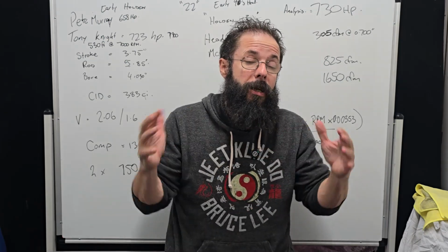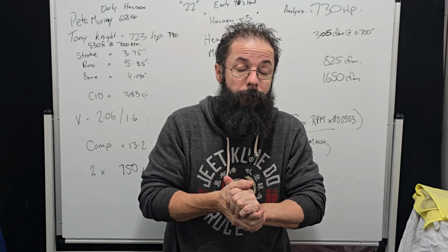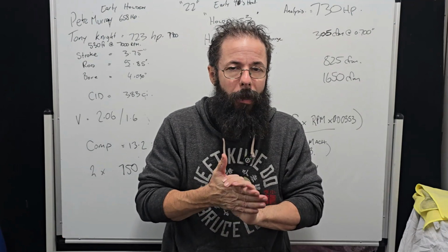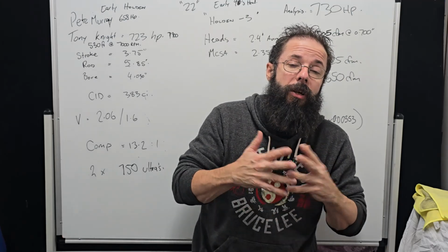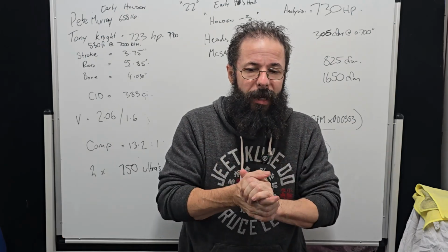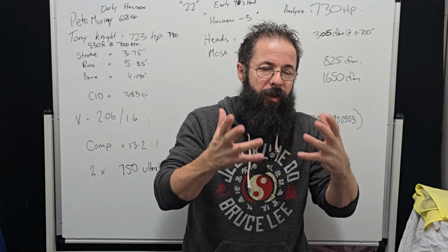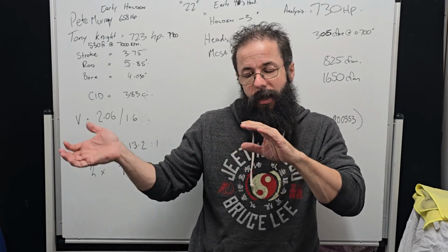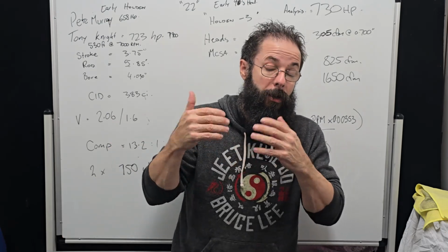So meaning we can go much bigger in the carburetor without sacrificing a lot of low end response that you'd see normally with a single plane, because they're turning the air so hard and the signal gets washed out. And also with a tunnel ram, they generally don't need shear plates or anti-reversion plates. And this is where you'll see a lot of people get confused with over-carbureting dual planes and stuff like that, and dynamic CSA shrinking, and that bad positive wave getting washed out by mechanisms like that.